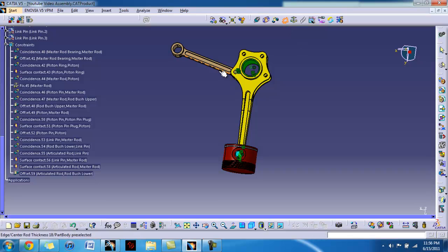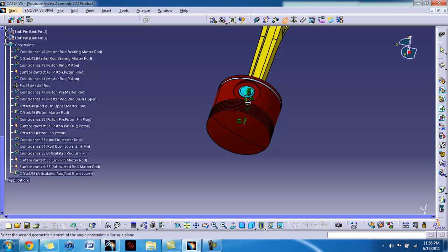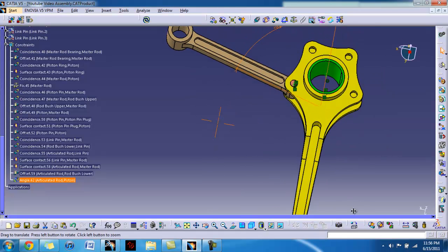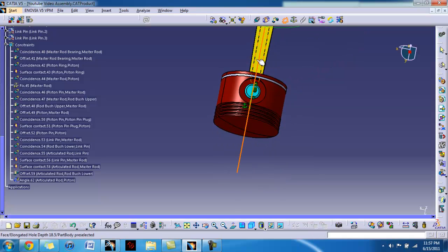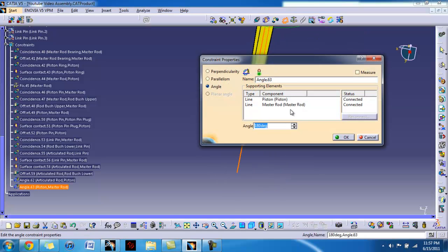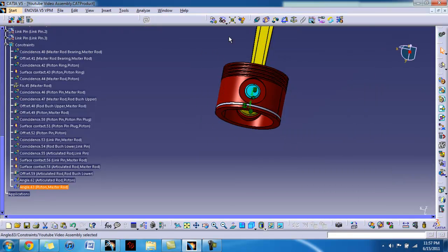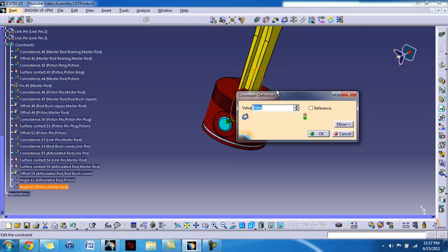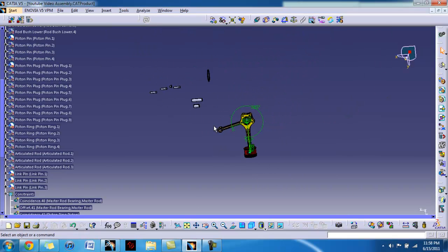Okay, you're going to select angle constraint, select the planar surface. Going to go in and select this center line axis here, 285. Hit OK, and update the angular constraint between there and here, and you want the angle to be 0. Hit update. Now you see it flips. So we're going to change it to the correct angle now, and the correct angle is 180 degrees, and you hit update, and we're going to zoom out so we can find where all our parts went, and you can